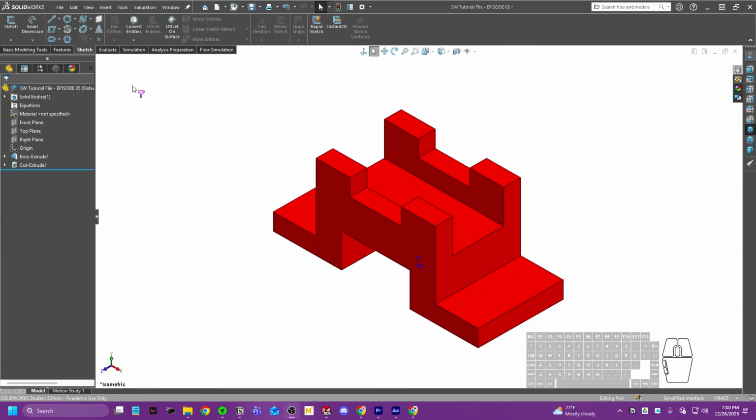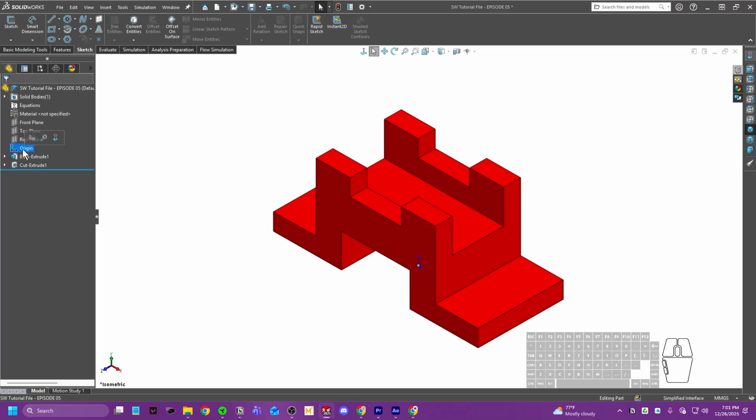Before we begin modeling, let's take a look at where the origin is going to be for this exercise. If you have downloaded the exercise file from the SDC Publications website and opened up the corresponding exercise for mass volume 3.5, you will see a part similar to this one. Mine is going to be colored, yours should be the color of the material that is assigned. Now looking at the origin, I can highlight it by pressing on the origin button in the feature manager tree, showing the origin at this location.